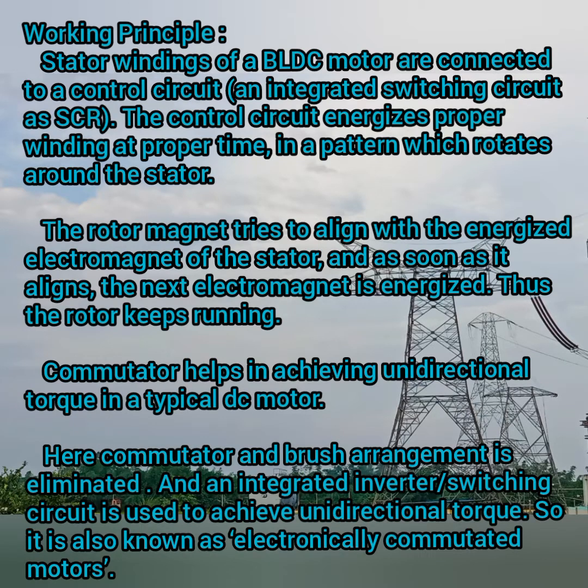Next, the working principle: the stator windings of your BLDC motor are connected to the control circuit. The control circuit energizes the proper winding at the proper time in a pattern which rotates around the stator. The rotor magnet tries to align with the energized electromagnet of your stator, and as soon as it aligns, the next electromagnet is energized. Thus the rotor keeps rotating in this way.